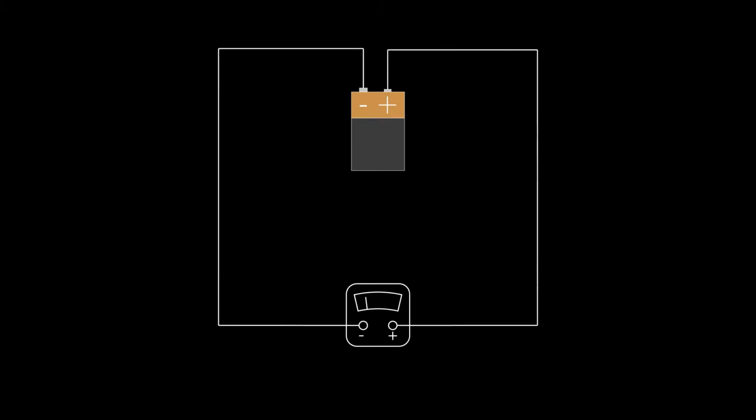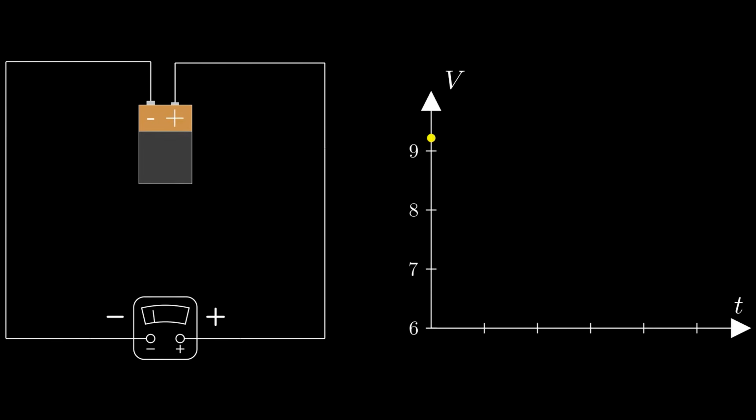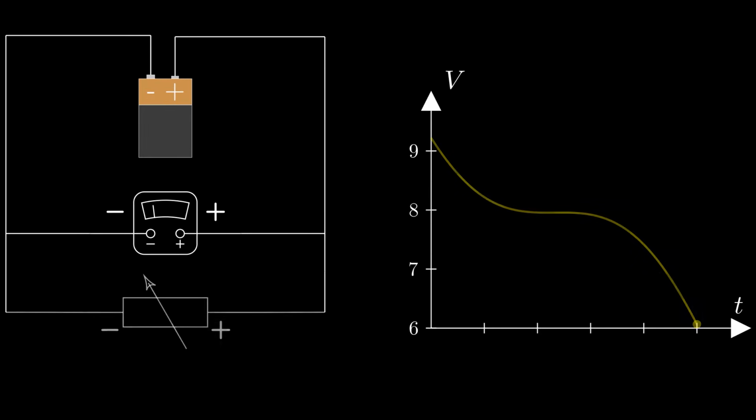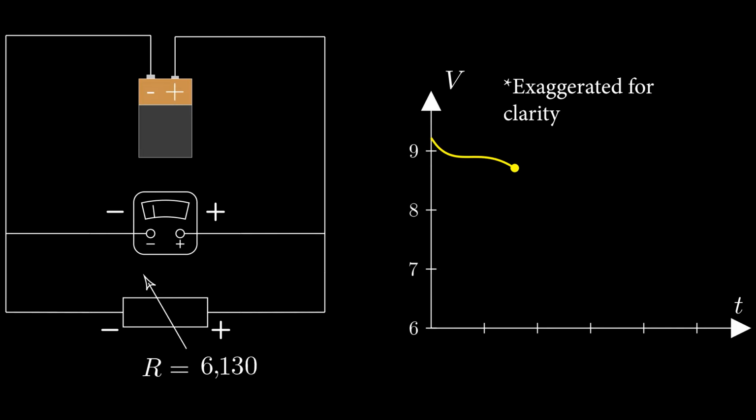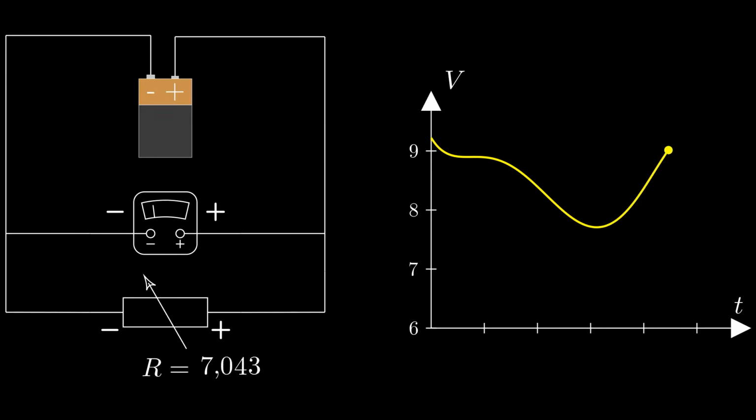Okay, so this is our 9-volt battery. It might start off with an output voltage at 9 volts, but as we use the energy from the battery, the output voltage begins to drop. So with no intervening circuitry, then obviously this change in voltage is going to be passed into our circuit, and we call this issue line regulation. On top of this, as we vary the load, this will also affect the output voltage, causing it to droop, and we call this load regulation.